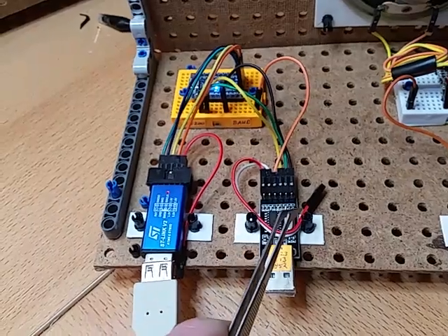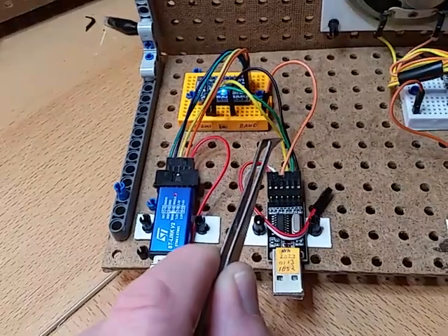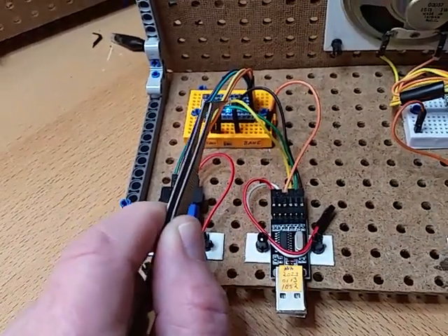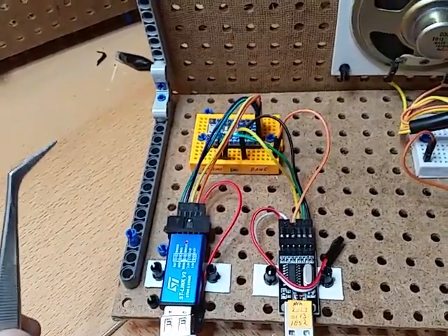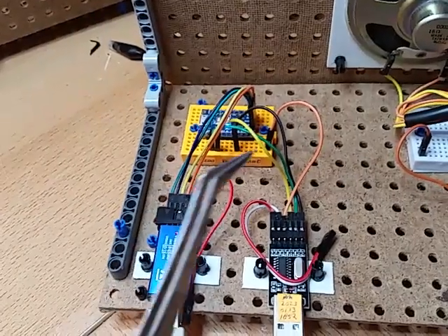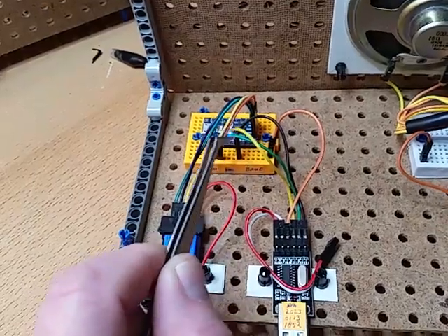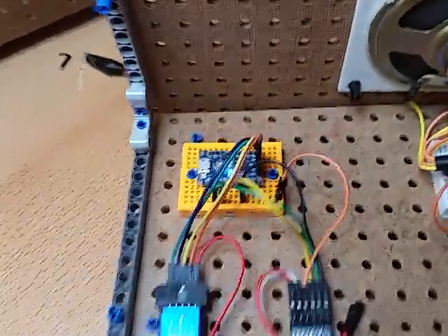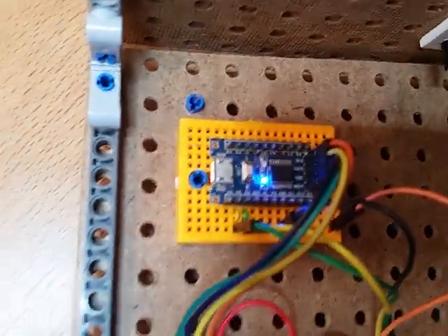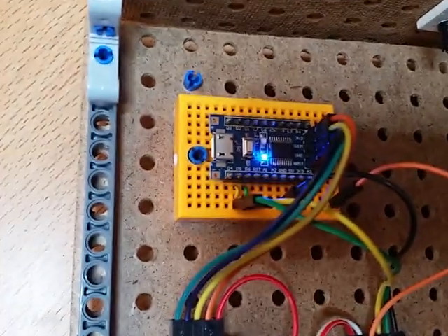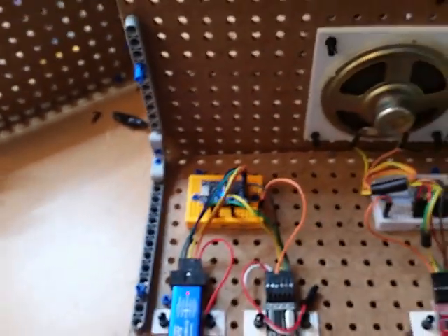RS232 interface. If I connect these together, the TX output will be 5 volt. Now it's 3.6. It's at the maximum that is allowed at the input of an STM. So I take a risk, but okay, we'll do that. The 3.3 going out is not used. Only the TX and the RX, the yellow and the green, are connected to the opposite color. The green to the yellow, and the yellow is connected to the green. So this should work serially.